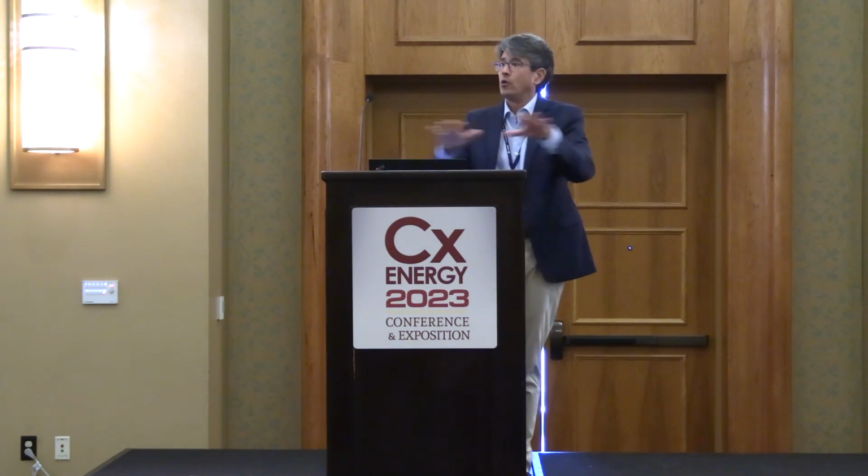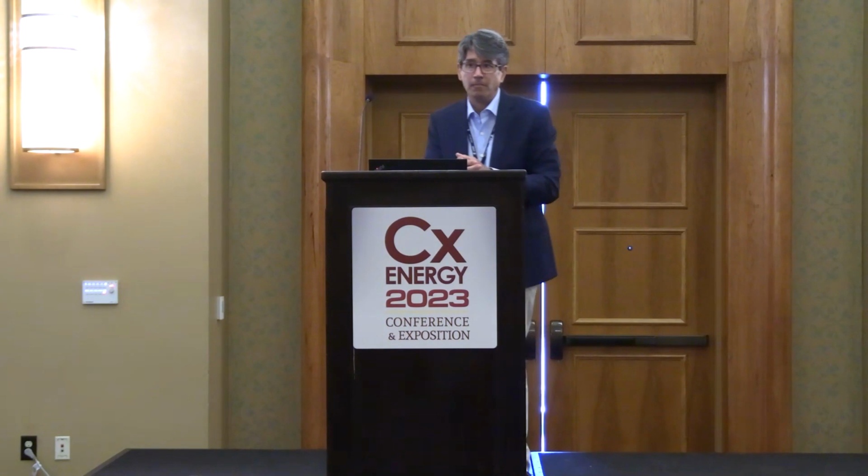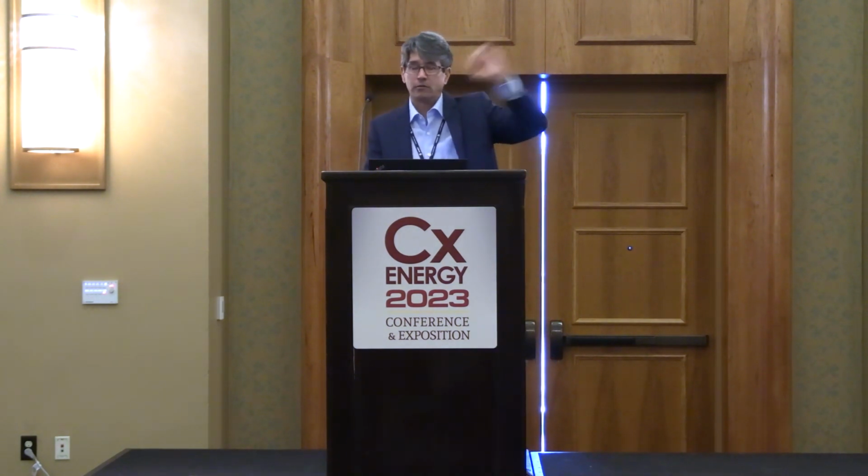But you've got to think, several times we're going to do exhaust fans. A lot of times we'll measure the exhaust fans, say, we need to know all the exhaust airflows through this school. We're going to replace them all. Or we're going to do this remodel. I can't tell you how many times we start doing that, and I bet you 50% of the exhaust fans no longer have electrical wiring to them. Belts aren't hooked up, et cetera. And it's always fun: no, we took the electrical off that. We don't use that fan anymore.